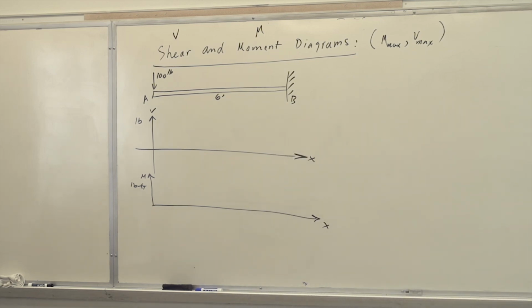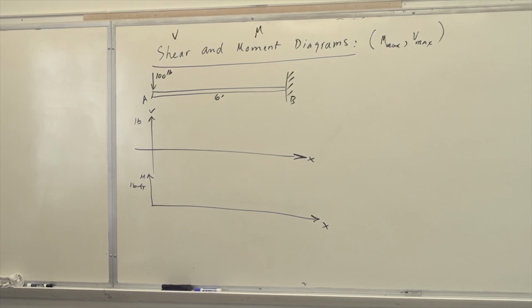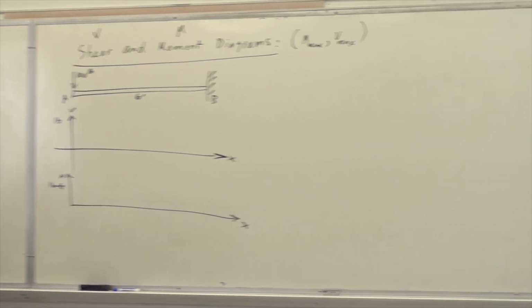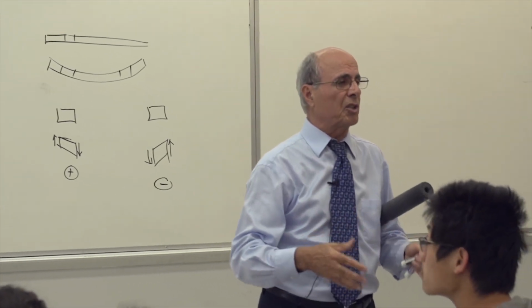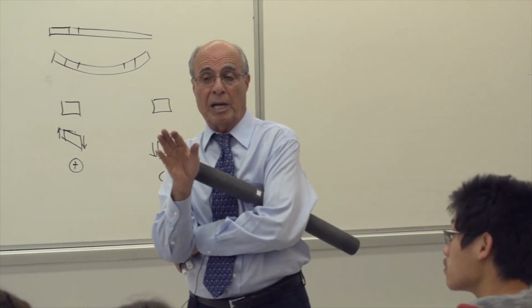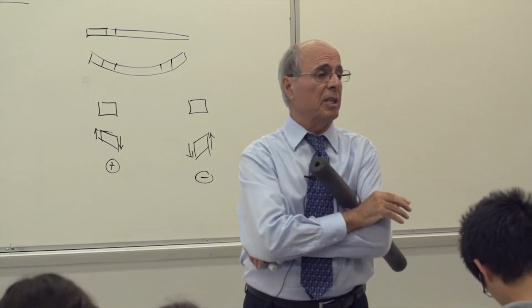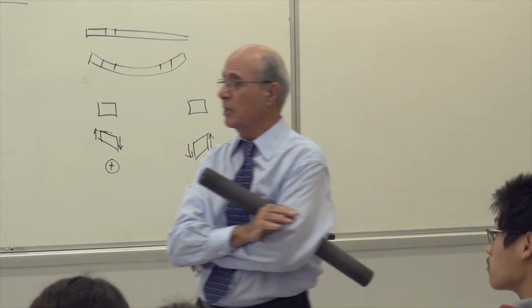I gave you a quiz in pound-foot, but that was a torque. This is bending. Remember the difference between that problem, which was a torque scenario, and this. This is bending. You have to calculate the M, then go to chapter 4. Chapter 4 was just the stresses due to the M. Is that understood? We did that. Some books actually explain this first, then calculate the stresses. There are different versions of that.